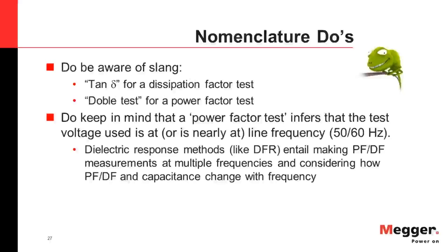And lastly, do keep in mind that when you're referring to tests simply as a power factor test or a dissipation factor test, you are naturally inferring that the test voltage being used is at or nearly at line frequency. Dielectric response methods like dielectric frequency response entail making power factor measurements at multiple frequencies and then considering how power factor and capacitance change with frequency.